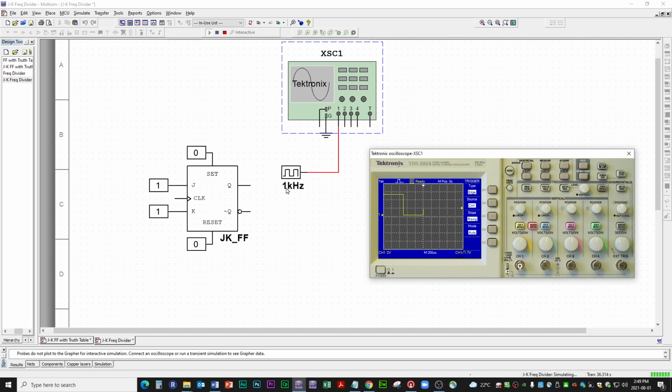Now, it should be 1 kilohertz. Can we see the whole period on this? Yes, we probably can, but we can reposition that so we can see at least one repetitive waveform. So let's say from here it goes up, here, down. Okay, so from here to here, it's a whole waveform, for example. Right? Goes on 0, goes up, and goes on 0. So from here, the signal starts repeating, from here to here.